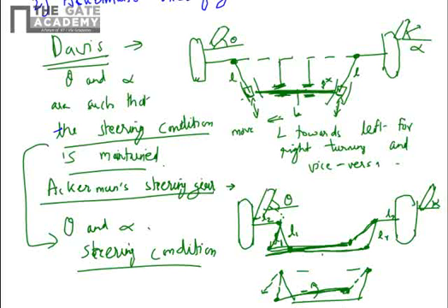And the disadvantage with Davis gear is that you have the sliding pairs. So because of sliding pairs, you have wear and tear and loss in accuracy of the steering. That is the disadvantage. Here the disadvantage in Ackermann is that the coupler link is having rotary motion. You have to take account of that when you are transmitting the steering from the steering wheel. So it will be transmitted from some other location at the driver's seat to this position. This angular motion also you have to take into account. And here in the Davis you have to take the wear into account.